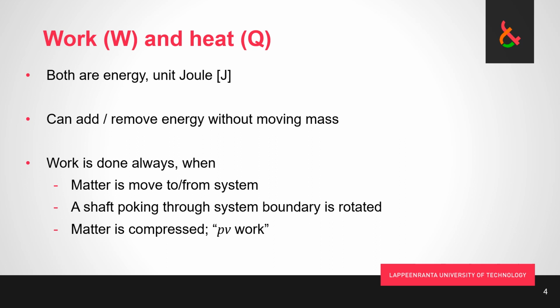And we always do work when we move mass into or out of the system. There's always work done, of course, basic mechanics. If we have a shaft poking through the system boundary and we're rotating that shaft, then work is being done either by the system or into the system, depending on where the force to rotate the shaft is coming from. And if we are compressing matter, we are doing work. We call that PV work.